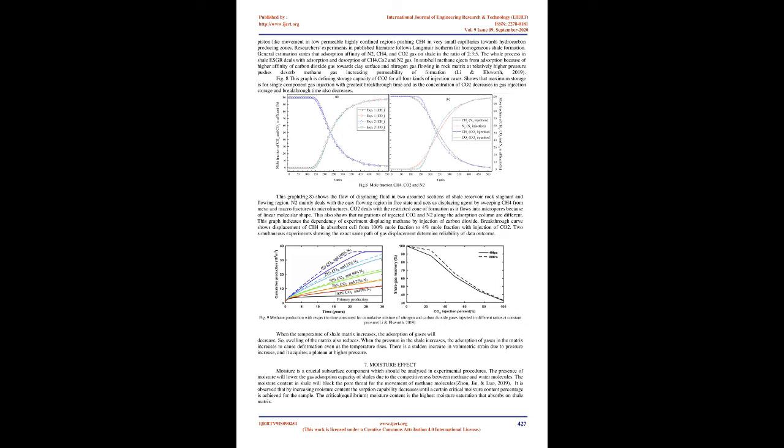Different Langmuir, 1918, equations for both processes justify the statement. The higher the value of organic content in shale, the higher the desorption rate with the increasing pressure difference. The adsorption capacity of shale varies for different adsorbing gases. The gases injected into shale are not fully released during production. When the pressure increases, the adsorbing capacity of gases is gradually increased and has the highest adsorbing capacity in the order of CO2, CH4, and N2. Adsorption and desorption curve for shale with different organic content, Guo, Hu, Zhang, Yu, and Wang, 2017.